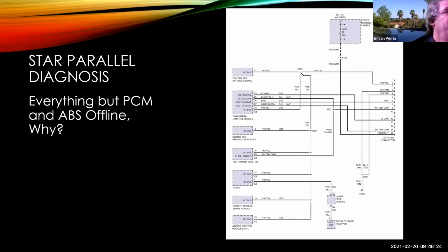So do I want to try to find splice 126? Do I want to try to find 201? Where do I want to go? Again, that's going to be based on accessibility. When was the last time you guys tried to find a splice in a harness? It's not fun, because they're usually only within about 3 feet of where they tell you. There is some component location, but they are hard to find even with the component locator. But that's where the problem has to be.